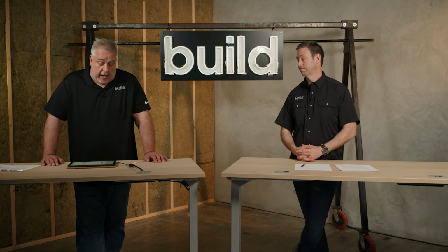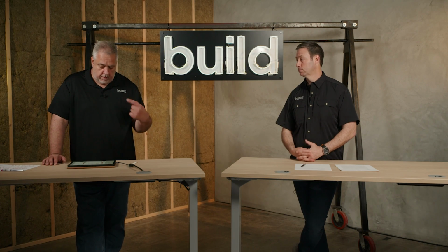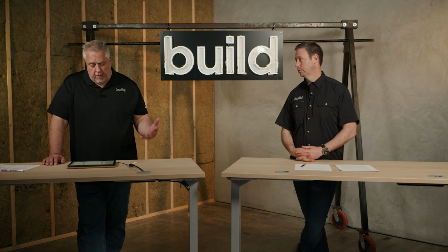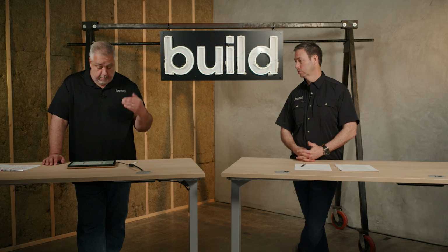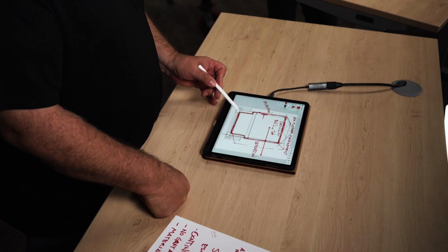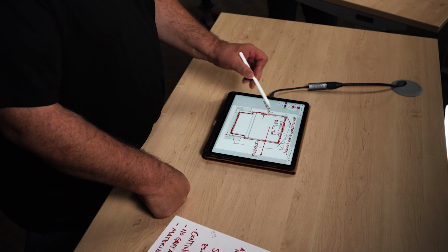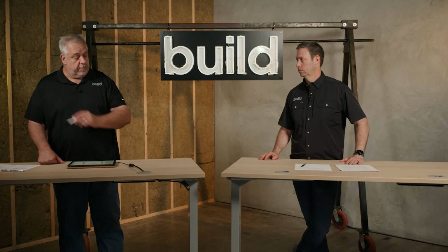So this blower door, this isn't just theory. This is practice, and this is you being able to get a certificate of occupancy from your jurisdiction where you build as well. Yeah. Now, 2 things about the blower door test. One, that you mentioned, it's becoming more prevalent and becoming requirements in certain locations. But I like to take it one step further, because when we build a house, we don't just build a slab, a foundation wall, an exterior wall, and then put a roof on it.